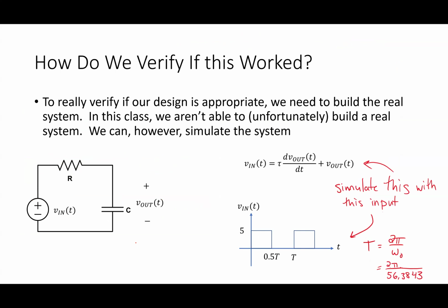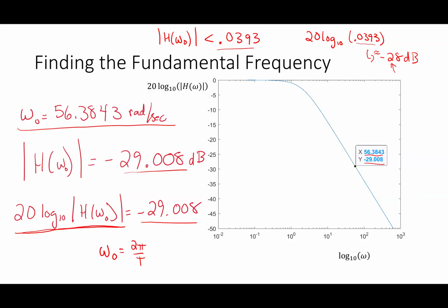What you end up doing in problem 3 is a very similar exercise. I give you a constraint. You have to translate that constraint into an equation like this, make this graph, and then choose a frequency. If you define a particular threshold, make sure that on the dB scale you're more negative than that constraint. That's because the log of a number less than 1 is a negative value, and the smaller that number gets, the more negative the result becomes.